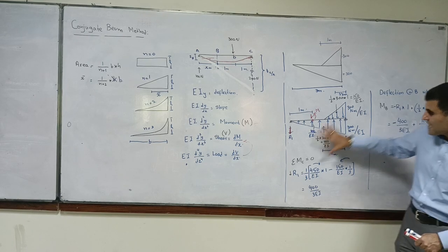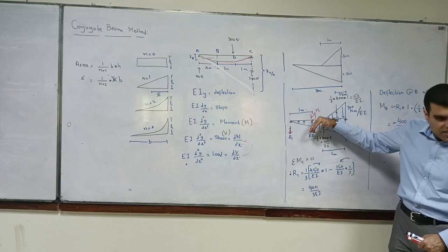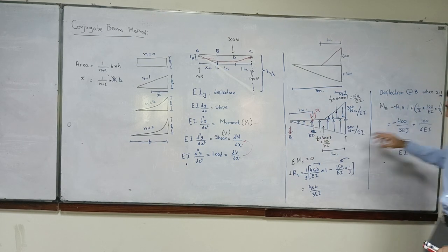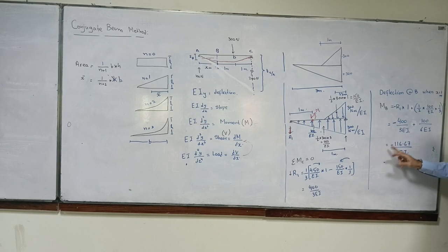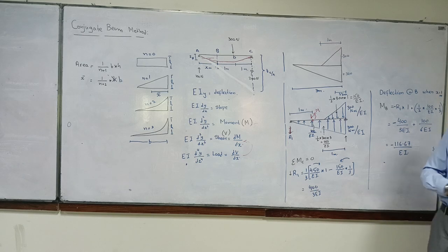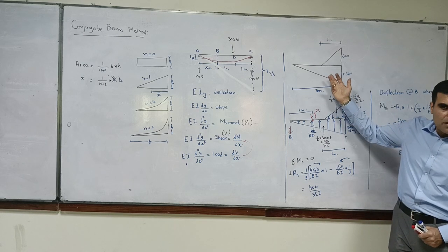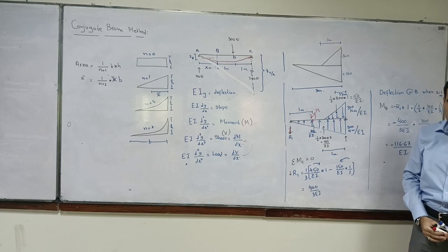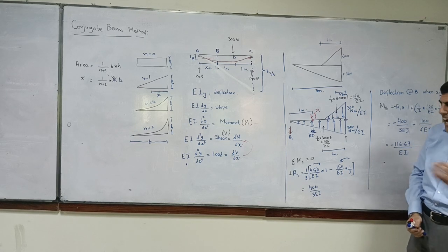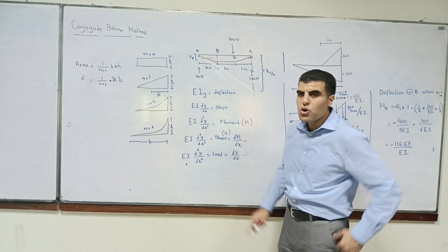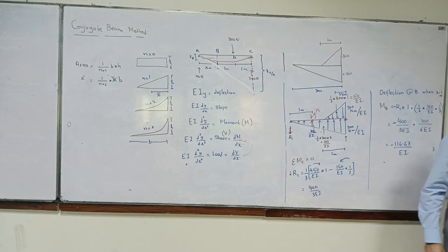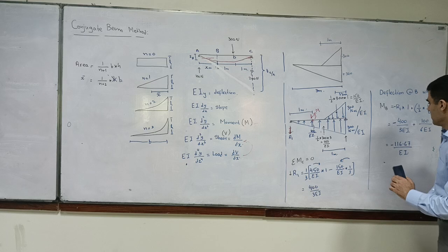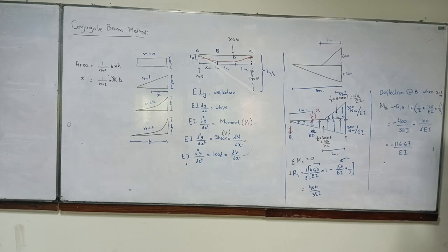So using this logic, we are assuming that the deflection is upward, but you get negative, which means that the deflection is downward. So you have to correlate your moment with the deflection. Do you understand my point? So moment and deflection, they are analogous. So you correlate. Okay, is this okay? Yes. Should I rub it off? Thank you, sir.